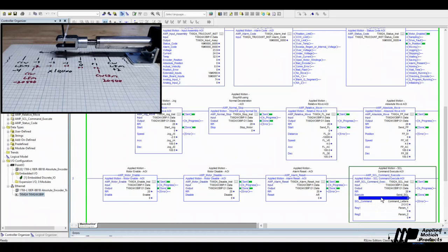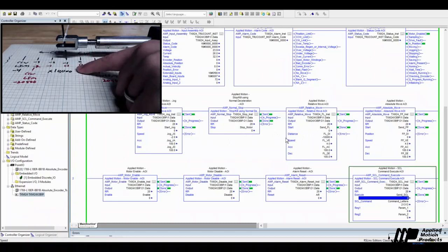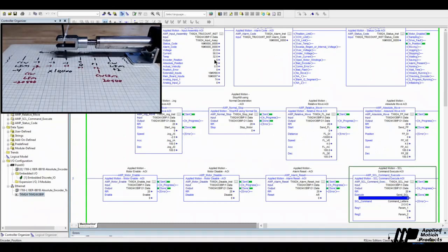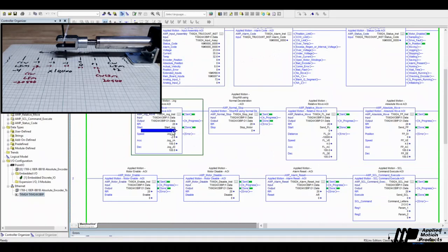We're going to send that, and now let's just do a couple of quick checks to make sure we're on the right page. So we're at our new home position, and we can see that we are at absolute position 0, so we know the home position took. And let's just jog and see if our limit switches took. We're going to hit right here, and if not, we're going to hit right here. Oh, okay, so our counterclockwise limit is good. And let's go in the other direction. We're going to do +4. And again, we should stop right there.